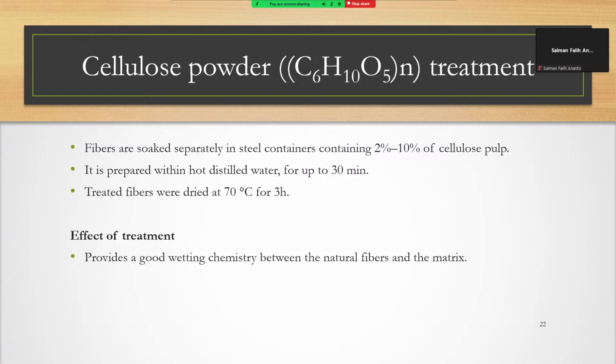The next is polymer coating. The polymer solution is made from 12% of A mixture, where A mixture means 48% acrylic acid plus 42% water, 8% styrene, 1.5% itaconic acid, and 2.5% acrylic diphenyl oxide disulfonate, along with 1% of B mixture. B mixture consists of 7.5% sodium persulfate and 92.5% water.